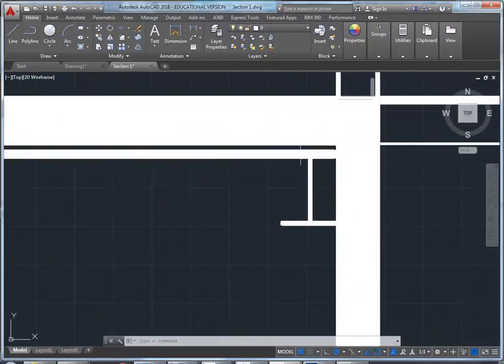Okay, so notice how here we've got a line just below the floor. So often people assume I can just make the bottom of my floor the ceiling, when in reality you can't do that, because you need to think about services. Unless you're using some of those new tricky structures, which you probably don't need to know about, but there are structures now where you can put things through the floor structure. But I've only seen them on TV shows and things. I haven't actually seen them in Australia yet, but you can do that. Oh, sorry, no, with steel structures you can do them here, but they've got timber structures now where you can go with services through the timber structural members, which is a pretty interesting thing.